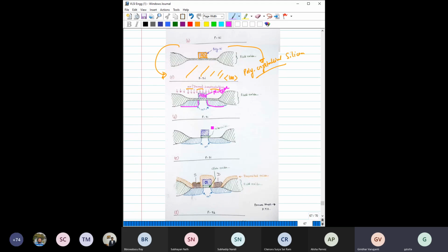And remember the RC loss, right? So this gate line, you have to understand in a 3D view. So this is this gate pattern, right? If you are connecting some potential here, if the resistance is high, this is the resistance and this is the capacitance, right? So this resistance also plays an important role in determining the RC delay, right?